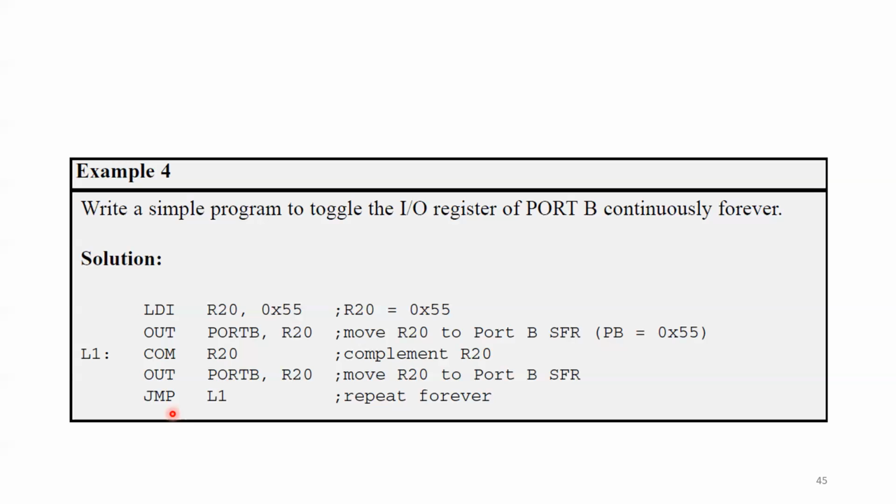In order to figure out that, you need to make a delay between each turning on and off. So in order to do this blinking for our LEDs, you need to add a delay after, for instance, this instruction, before jumping here. Make a delay for a certain time, let's say several hundreds of milliseconds, in order to see the change of the LED lights, okay.